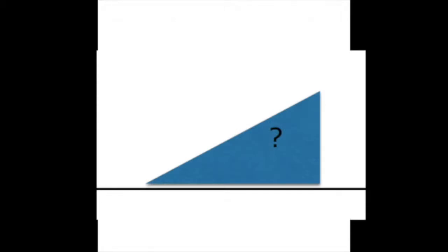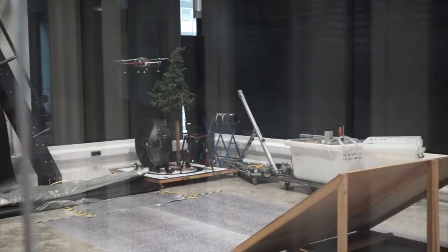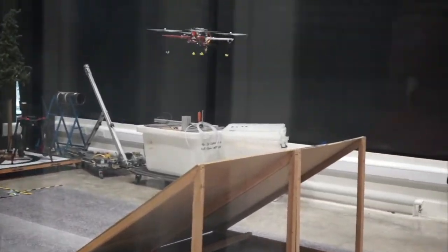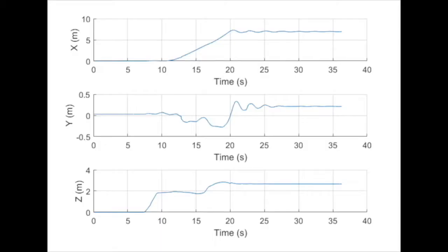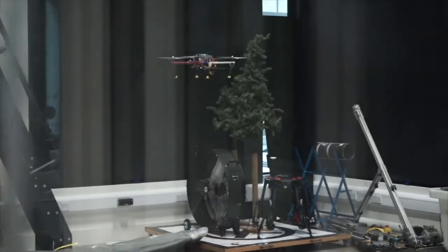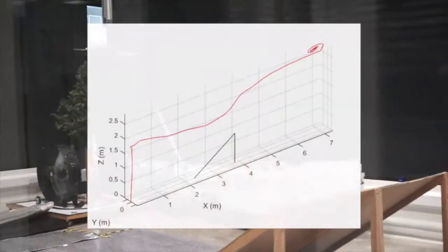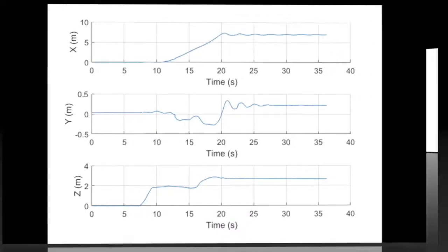In actual experiments, we test the drone twice, having a simple ramp as an obstacle. Test using camera, the drone took off and hovered nicely. For some reason, the drone lost some altitude during cruise. Detection of the ramp was pretty responsive, as expected, although the drone experienced large overshoot as it descended. In the second test using optical flow, the drone performed relatively well from start up to climbing the ramp. After that, errors seemed to build up and the drone did not descend properly and went straight to hit the nets in the end. This then leads us to discussion of the reality gap.